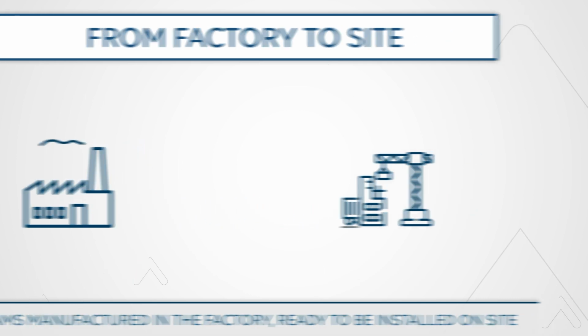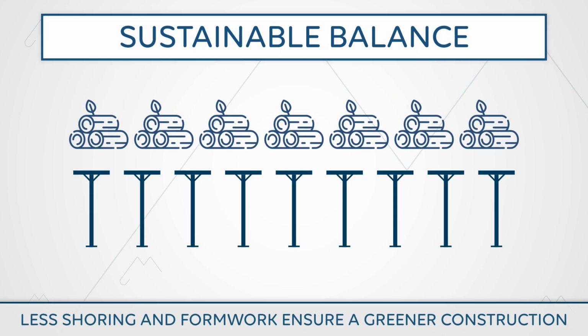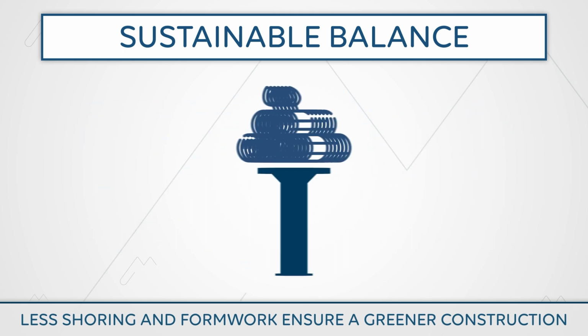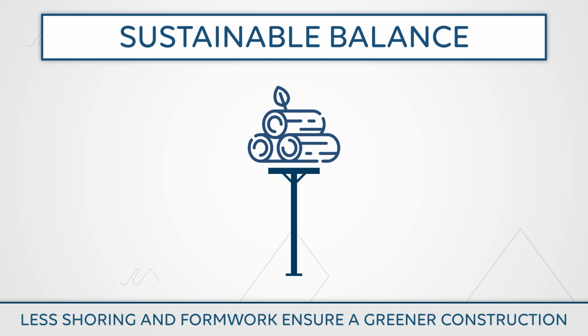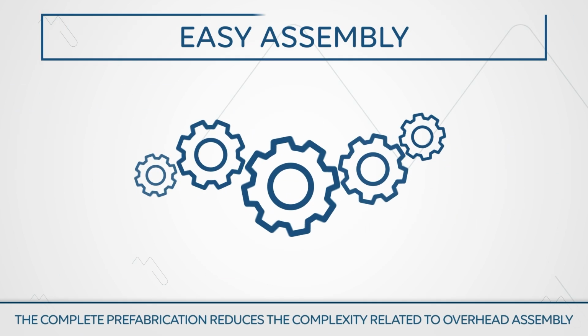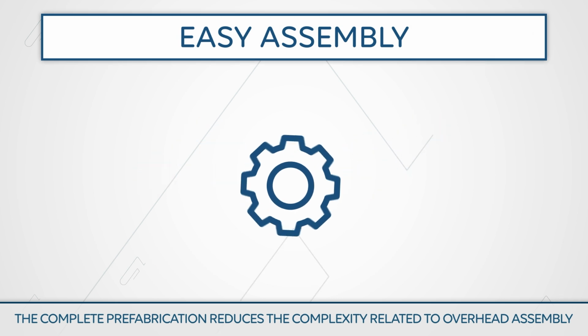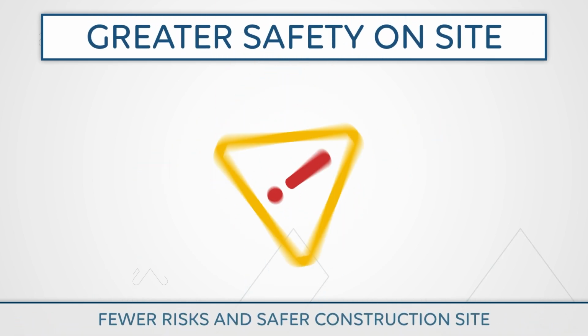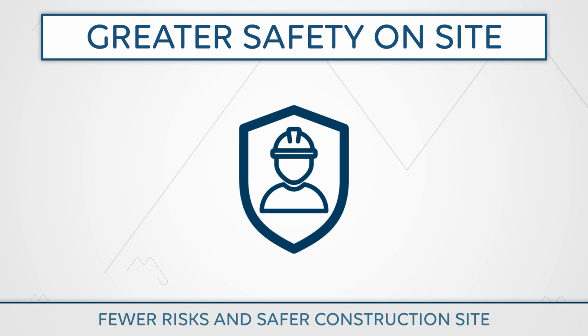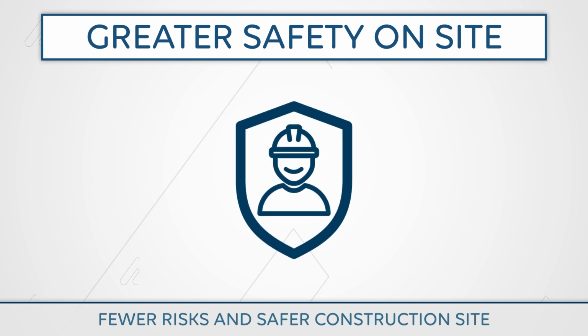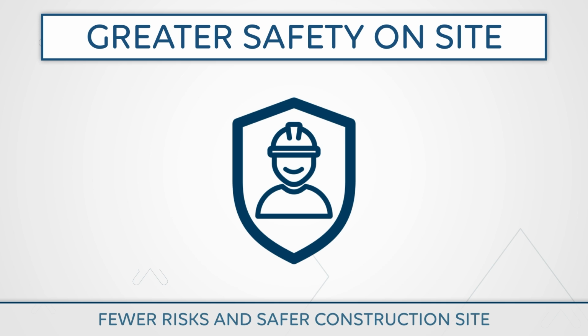With the MTR system, the amount of work on site is reduced. Formwork is also largely reduced with MTR beams and is totally removed from the MTR A beams. By reducing or totally eliminating shoring and formwork, the additional cost of running a building site is optimized. The use of the MTR system in combination with any type of floor leads to 100% prefabrication of the horizontal structure.